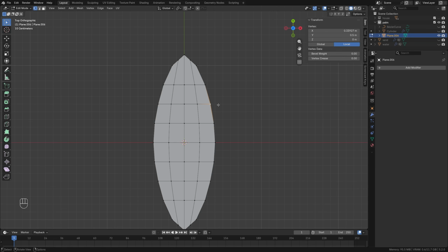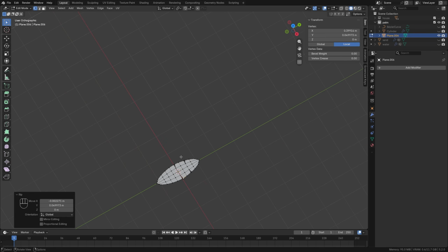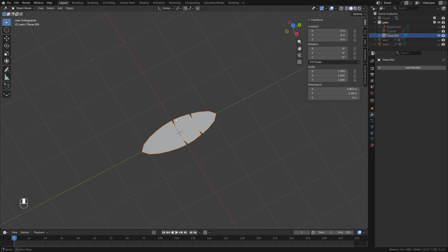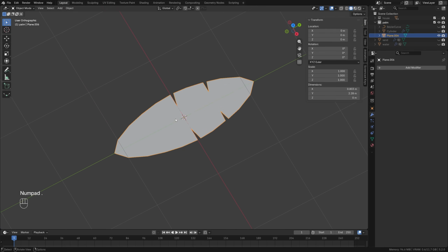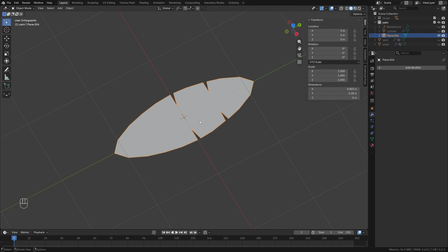And here we can select a vertex, press the V key, and move it to the side. For example, raise this one up, flatten this one here. The same thing applies here. We press V, raise it here and somewhere in the center, 1 and 2. In this way, we cut here and create the following element. Now, being in object mode, to concentrate around our leaf and comfortably rotate, you can press the period on the numpad keyboard, or in the View menu, select the item Frame Selected. That is the same thing.